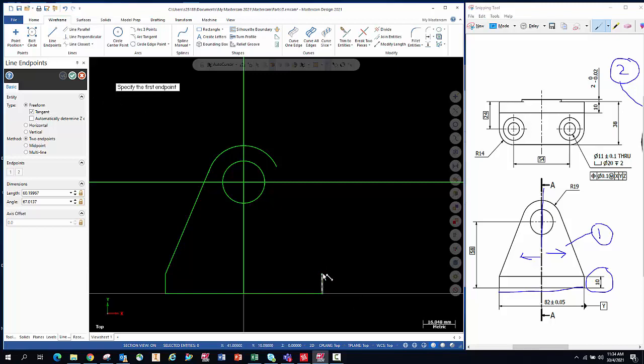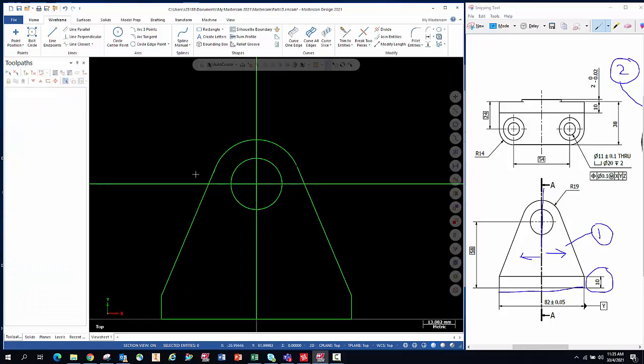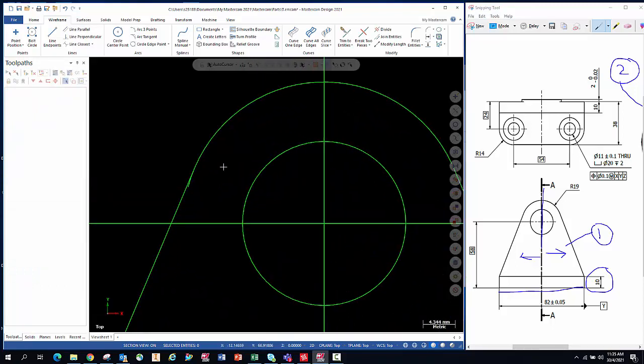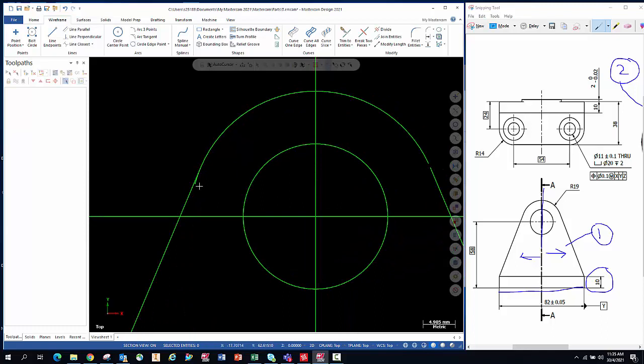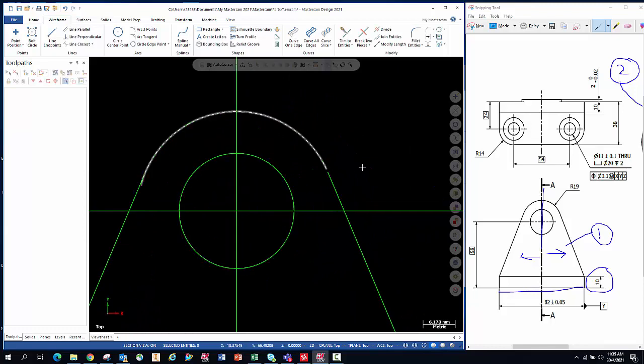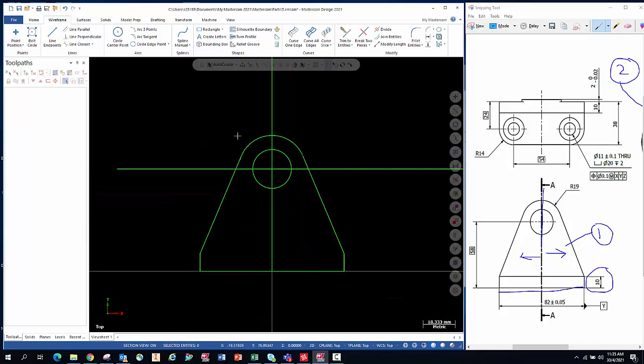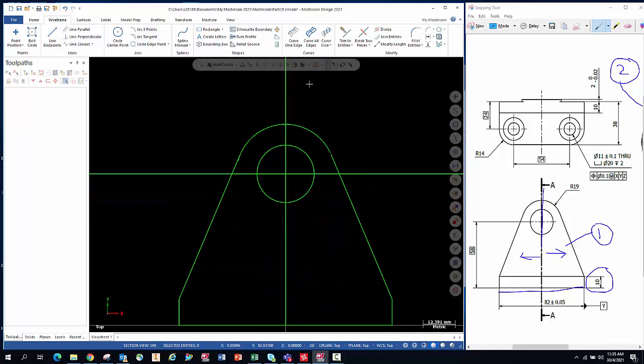Over here I say this is a point and this is the arc. So you can see that now on one end, because when I did the arc at the time, I did it slightly longer. So there is success. On the right hand side, I did the arc shorter. So in that case it is trying to tangent. However, because this arc is too short, the tangent point is actually over here. Okay, we could fix the problem using the trim command.